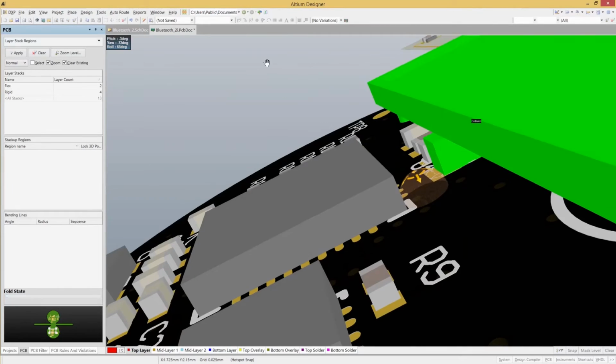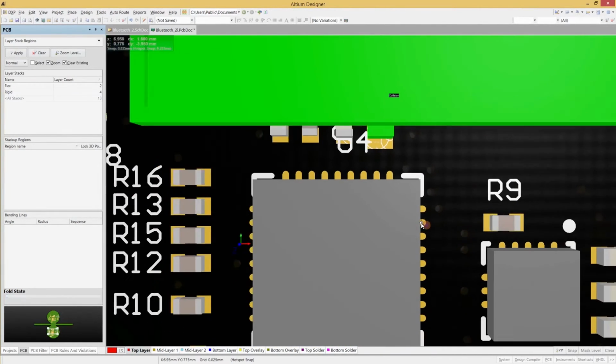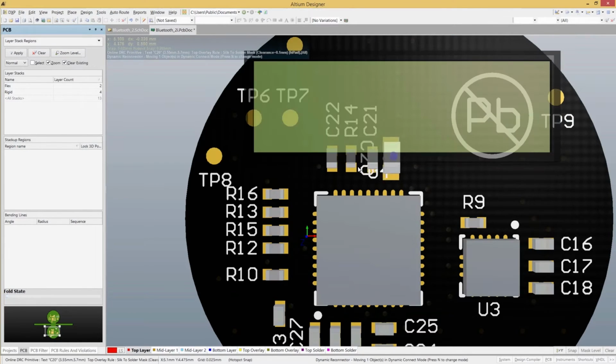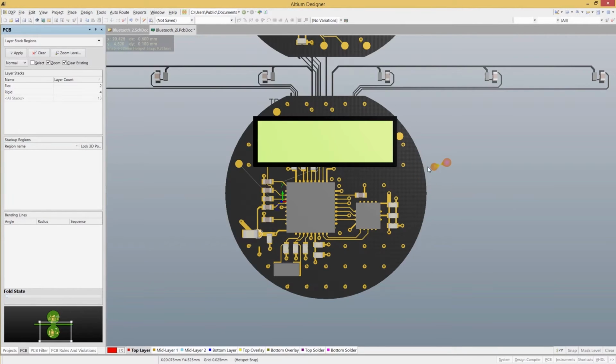So now I can see those components I previously placed underneath actually fit underneath that screen, but now my C20, it doesn't quite fit, and I'm going to need to go ahead and adjust that, move that to avoid that collision. Now I don't get rejects back to say, hey, we can't assemble this quite right. Although it worked electrically, it didn't work in terms of a fit.